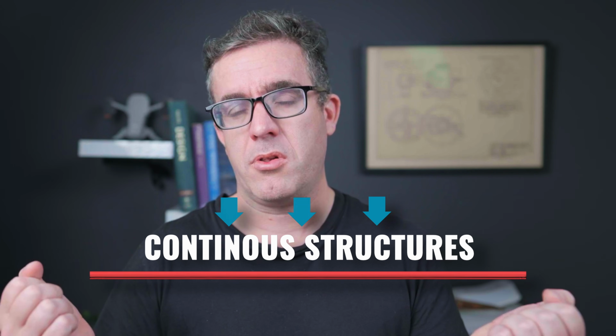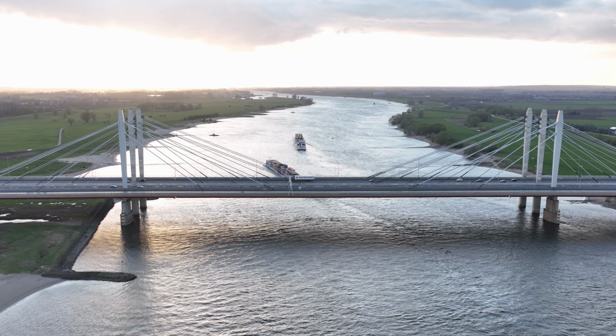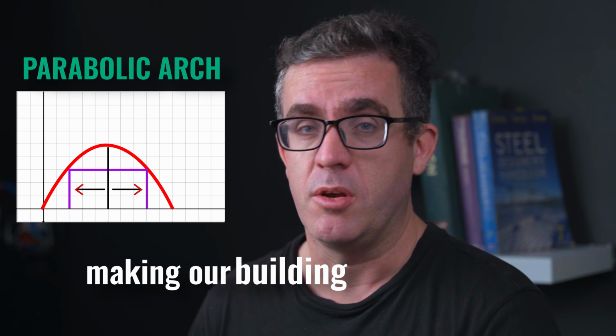So when you're looking at continuous structures, not only is it the force that is applied, but how much it will sag that will determine the tension force in those continuing actions. So if we're looking at a suspension bridge, we can see the nice arch behavior of the structure. It's trying to go into the most simplest form. The tighter it goes, the more force it needs to have to resist the same load. So that parabolic arch is actually helping us reduce the stresses and making our building more efficient.